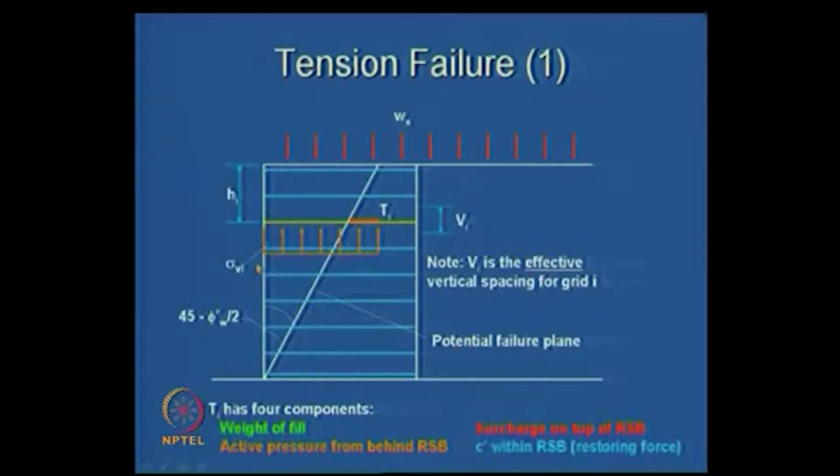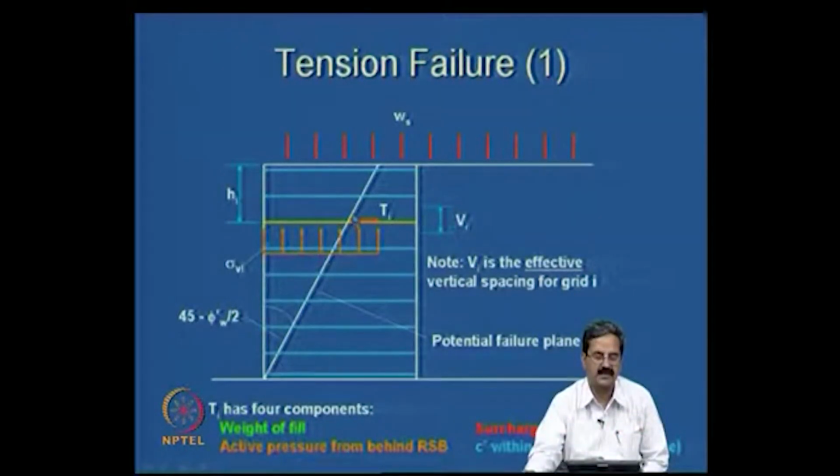So, at any level hi, you can always calculate the vertical pressure acting, total vertical pressure, and for that you are actually calculating horizontal force. You put Ka times vertical pressure, you will get the lateral pressure, and then design for Ti.